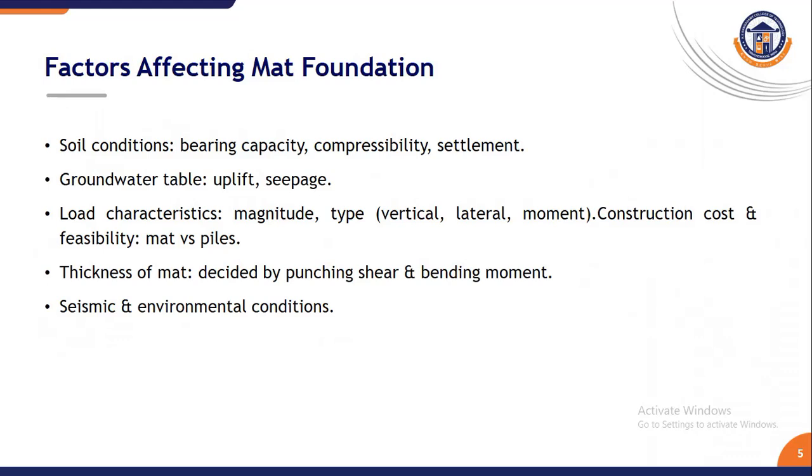Okay, right? And then the thickness of the mat should be based on the bending moment and punching shear around the column, so this is also mainly considered in mat foundation. Also, in the Gujarat earthquake of 2001, buildings with raft foundations performed better than those with isolated footings.